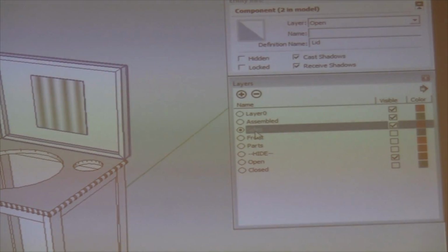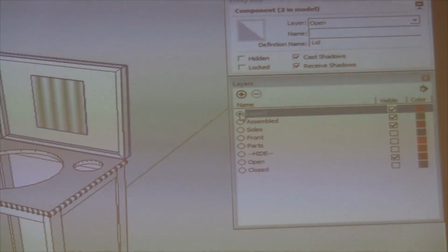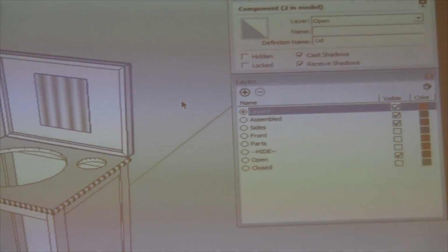If you ever want to move it off of that layer to somewhere else, you just create all kinds of grief. So the rule is, regardless of what the tool allows you, never ever ever draw anything except on layer 0. So layer 0 basically is all layers, and then if you do your drawing there and then select where you want it to be seen.